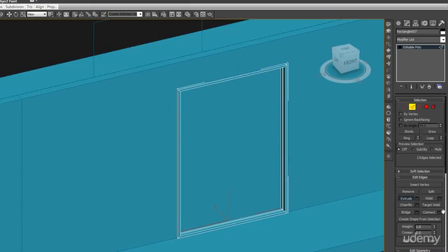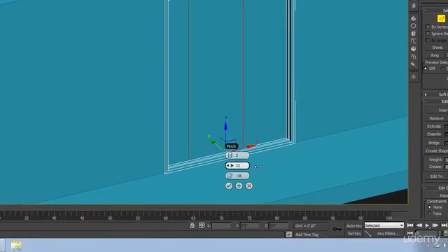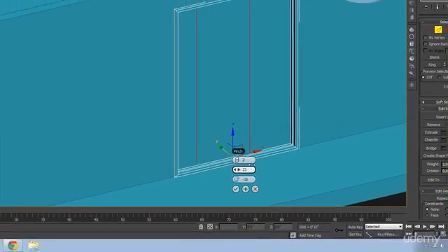Then we will connect, and we'll hit the dialog box, the settings for connect, just so I can show you. We're only going to connect it one time, and that'll connect it once right up the center of that thing. If we wanted it off the center, we could slide it in either direction. If we had two, we could pinch them together or stretch them apart like this.